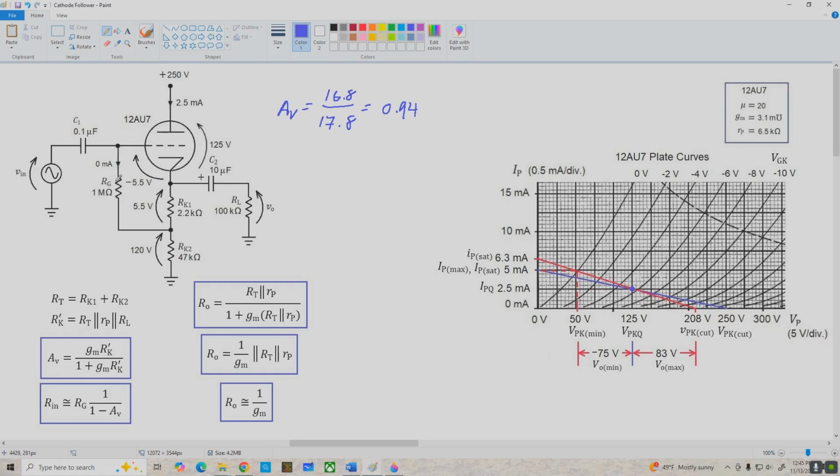In this case, this acts like a feedback resistor that's in a non-inverting amplifier, so we're going to get a larger value. Now, as long as our gain is less than 1, we're okay here. If our gain was larger than 1, this would actually probably turn this amplifier into an oscillator, and we don't want that. But in any case, this is something that's called bootstrapping, and we'll talk about that in another video.